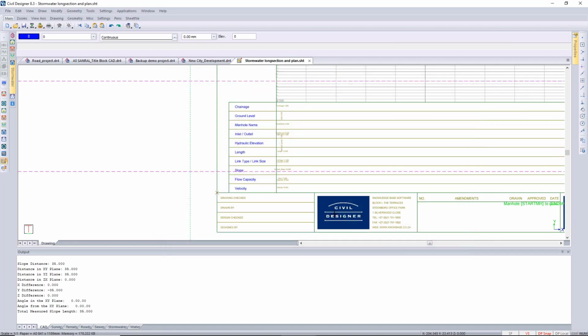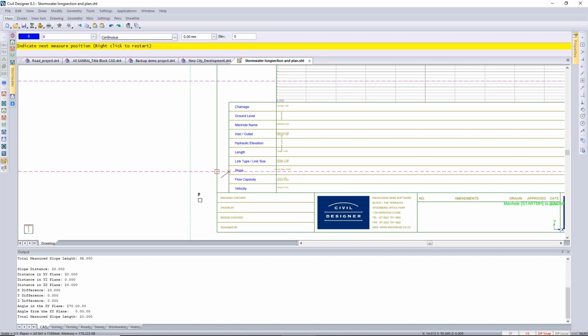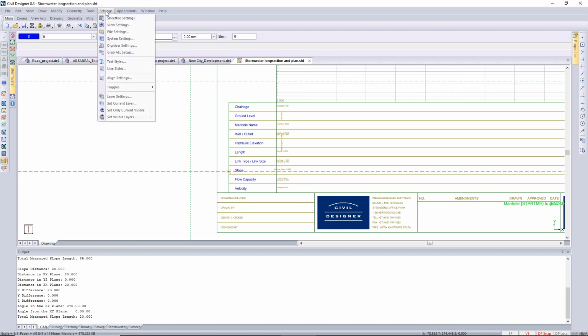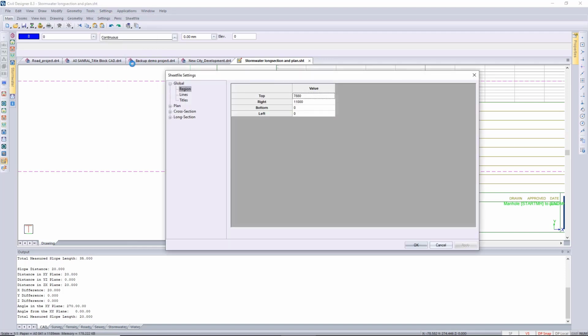Okay, and then we have to look at the horizontal spacing distance that we're going to have to adjust. So I'm going to just do a Q once again, just to measure from that point to that point. So it's 20 millimeters, which in tenths of a millimeter inside the sheet file would equate to 200 tenths of a millimeter.